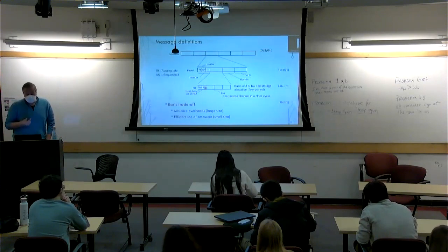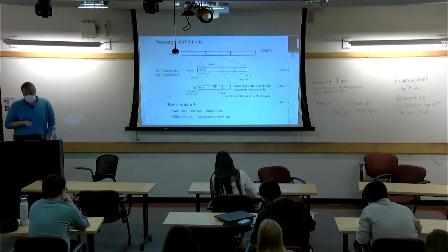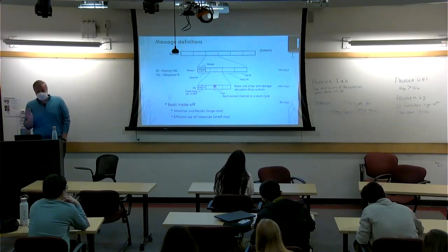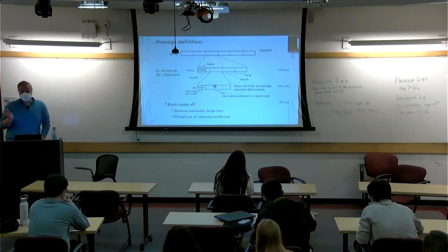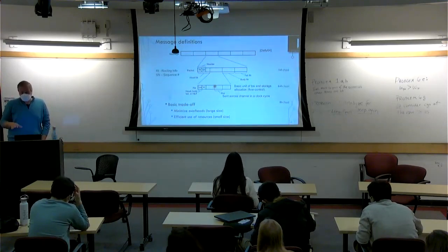It's an indicator of where you're going, in a sense. And then it can also be chunked into even smaller pieces that are typically around 8 bits in size. So flits are typically around 64 bits, and then phits are essentially around 8-bit chunks. Those are the smallest pieces you send across the wiring channel between two switches in a single cycle. But these are just typical numbers.